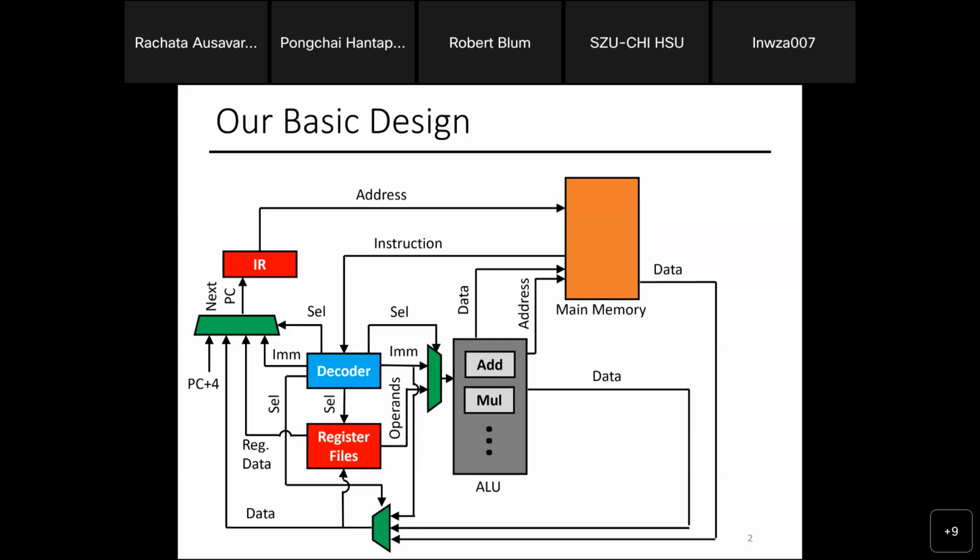Then there's the execute unit, which is the ALU that performs the instruction. Then there's the memory, which these days is getting a lot more important, because everything else here is quite possible to make faster really rapidly. I would say it's not easy, but it's possible. Your CPU gets faster quite quickly compared to your memory. The memory becomes the slow guy: I know I can get faster, but not at the same rate as the CPU. So the speed gap gets bigger and bigger, and memory becomes another important part of the CPU design.